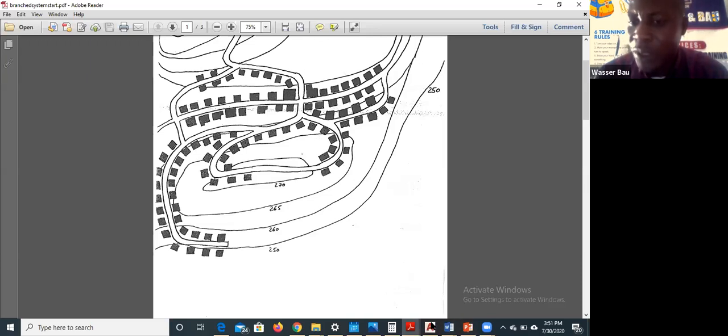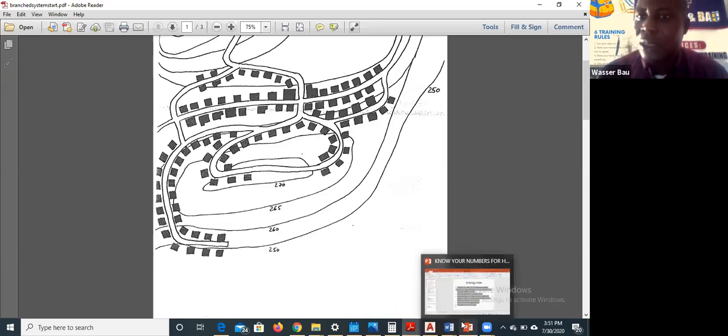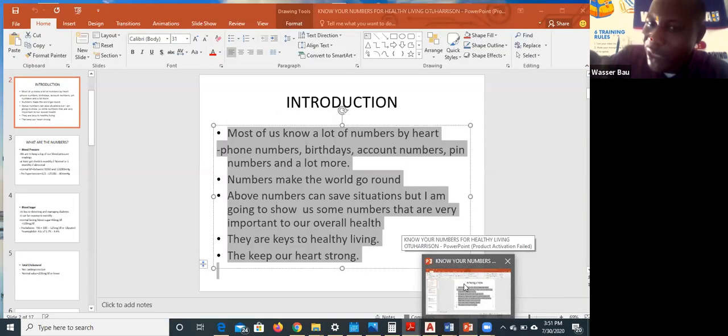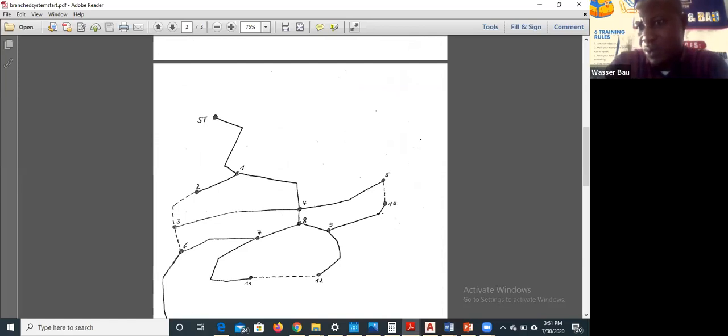But it is the pipe that's passing through the house, to use layman's language, it's already discharging to node 10 and to node 12. So the total demand in node 9 is not 0, but the base demand in node 9 can be 0.